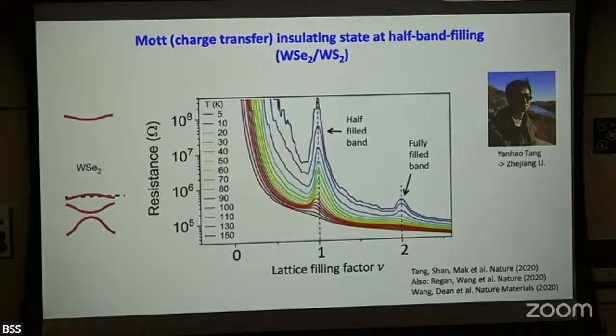But if it's some kind of metal, you get a very good contact. So contact resistance always strongly depends on the doping density of your material. This is the key to achieving good contacts, and that's the approach we use to reduce contact resistance.